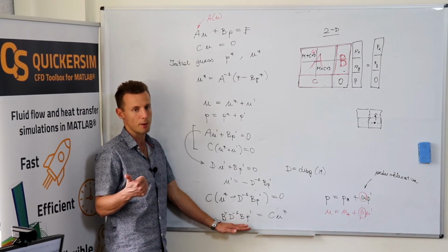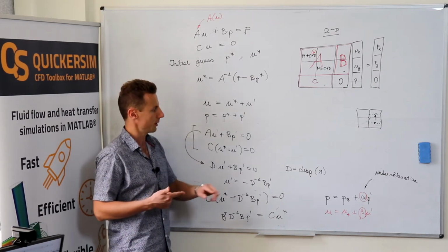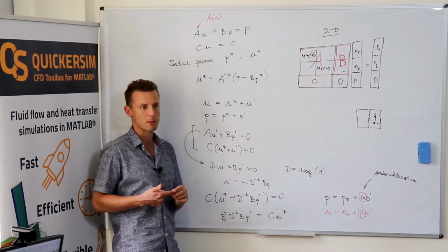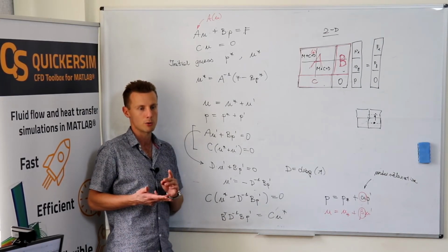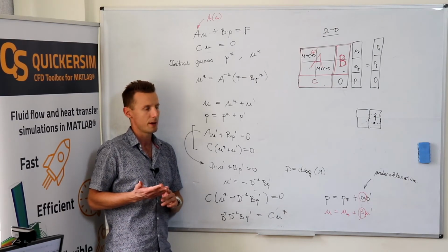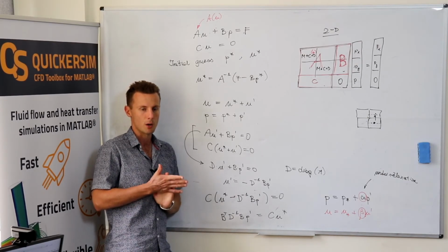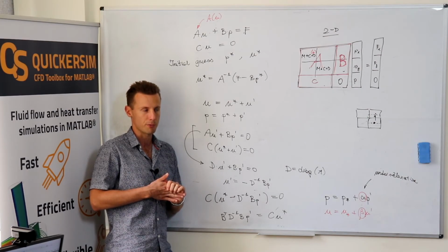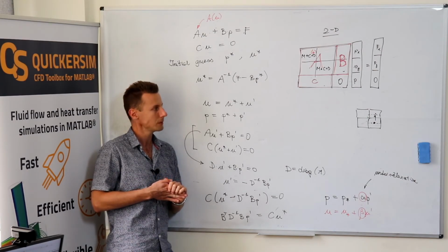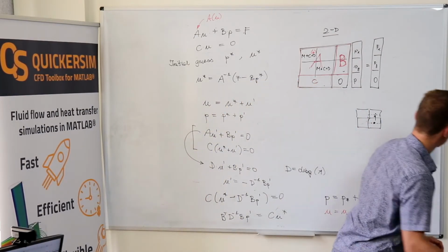direct solvers are one group of solvers. The iterative solvers, like based on the Krylov subspace, like conjugate gradients, biconjugate gradients stabilized, GMRES, probably MinRes also. They are iterative solvers based on the Krylov subspaces. There is also yet another class of solvers based on the concept of algebraic multigrid, and the algebraic multigrid comes from the observation that if you've got